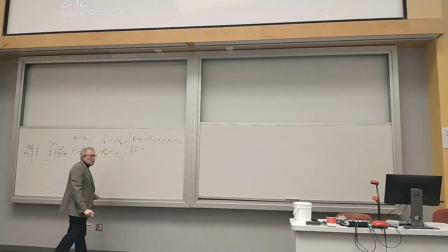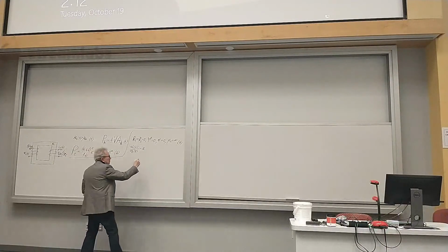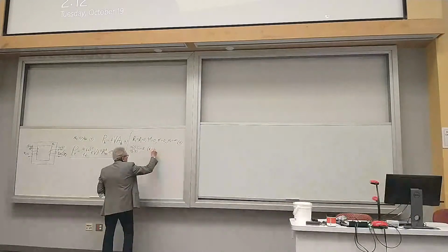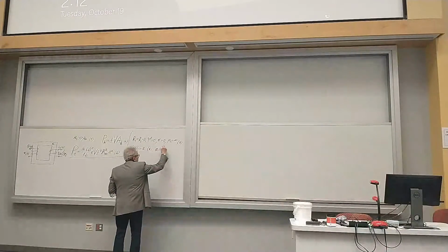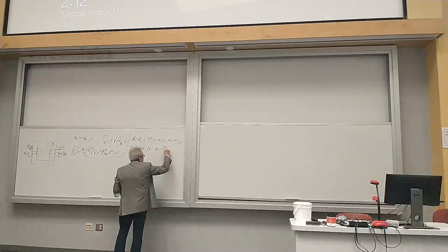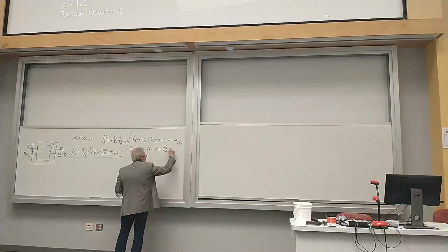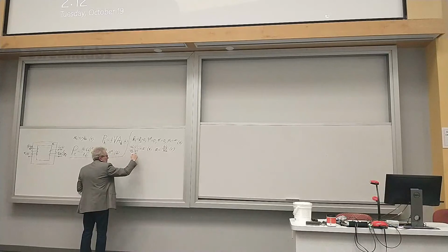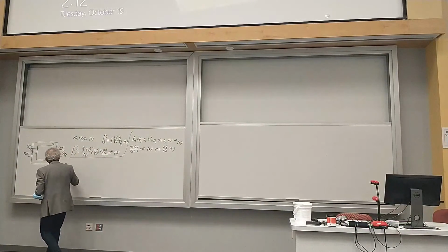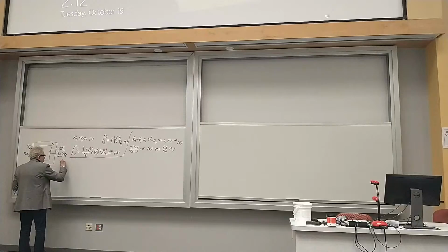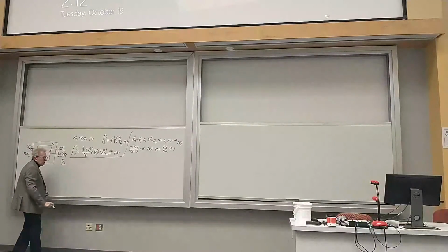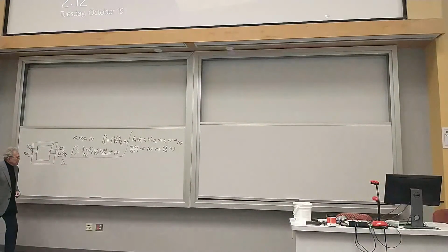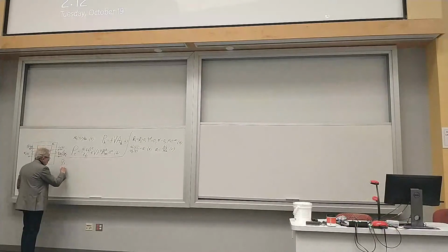We use the notation A for the turn ratio, where A is the ratio of the number of turns of the primary winding to the number of turns of the secondary winding. Similarly, I proved that this formula can be written in phasor form: in the case when we deal with sinusoidal voltages, the ratio of the phasor of the primary voltage to the phasor of the secondary voltage will be equal to A as well.